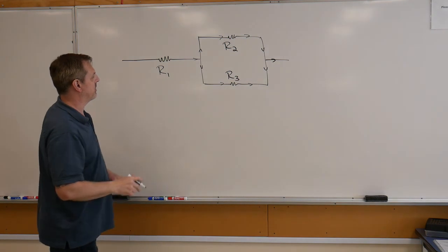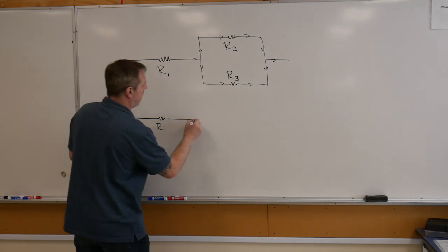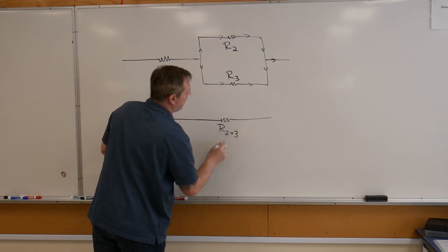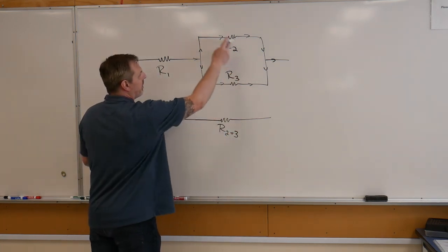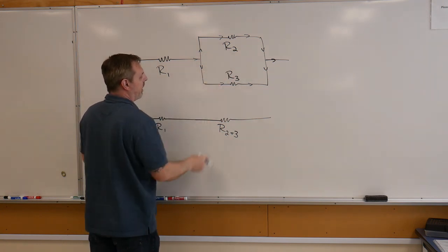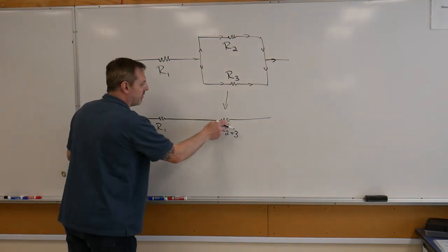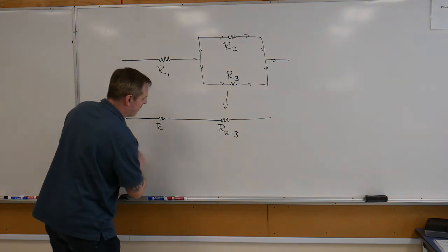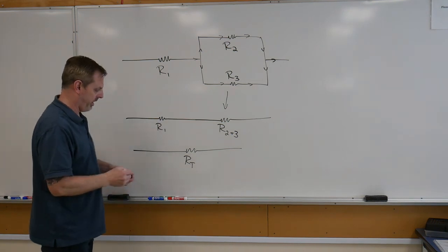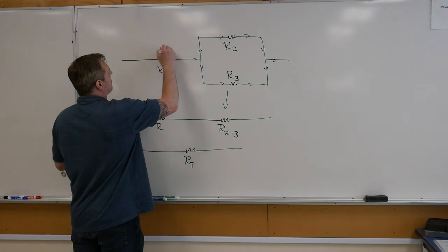If we simplified this circuit, we could look at R1 as still connected in series now to the resultant of R2 and R3. This resultant here is the parallel R total, or resistance total, for that circuit. So that is what that would then turn into, and we look at this value of resistance and that value of resistance, and we would then create the R total. Okay? If I applied values to this, let's give them all 10 ohms.